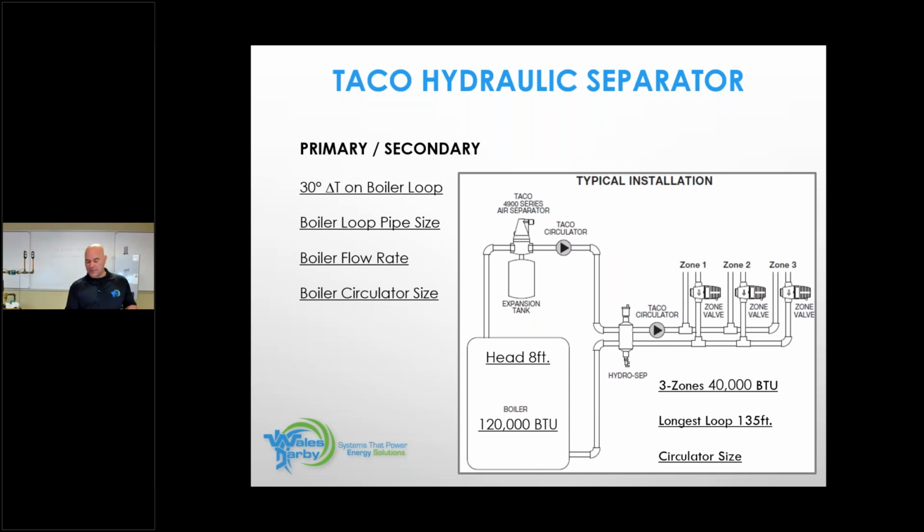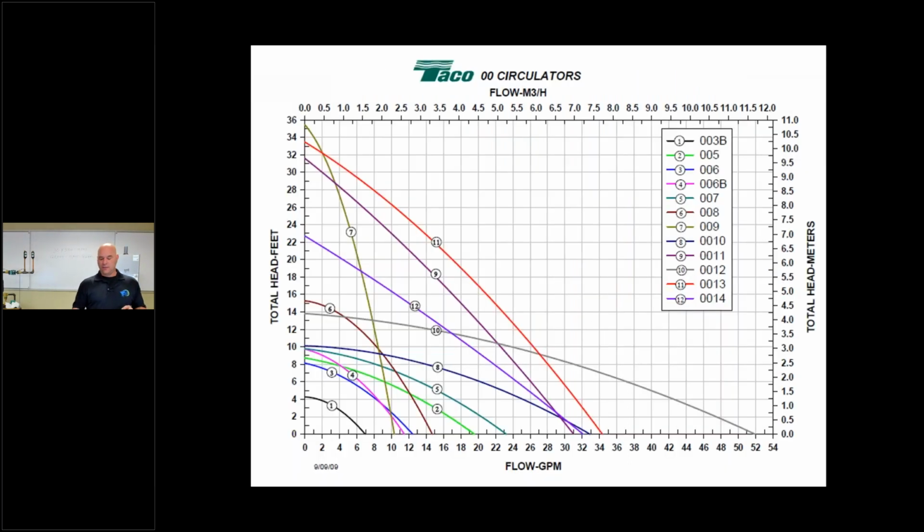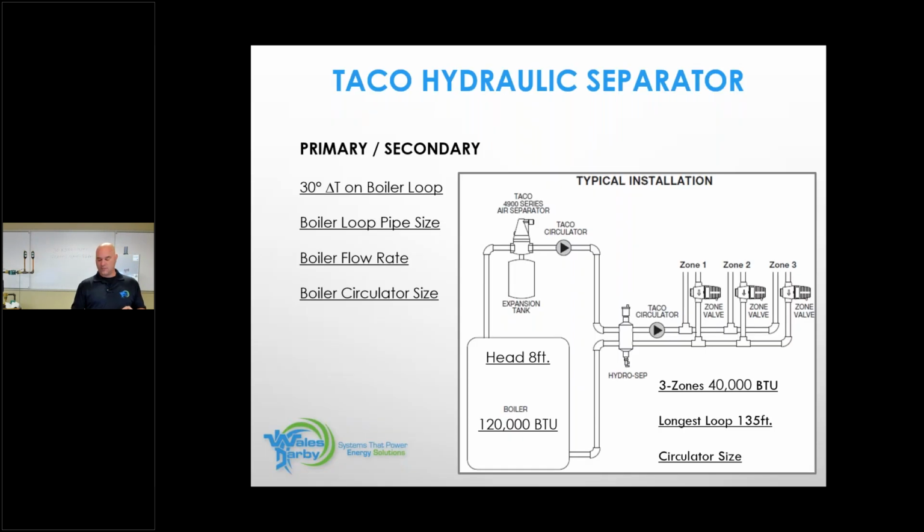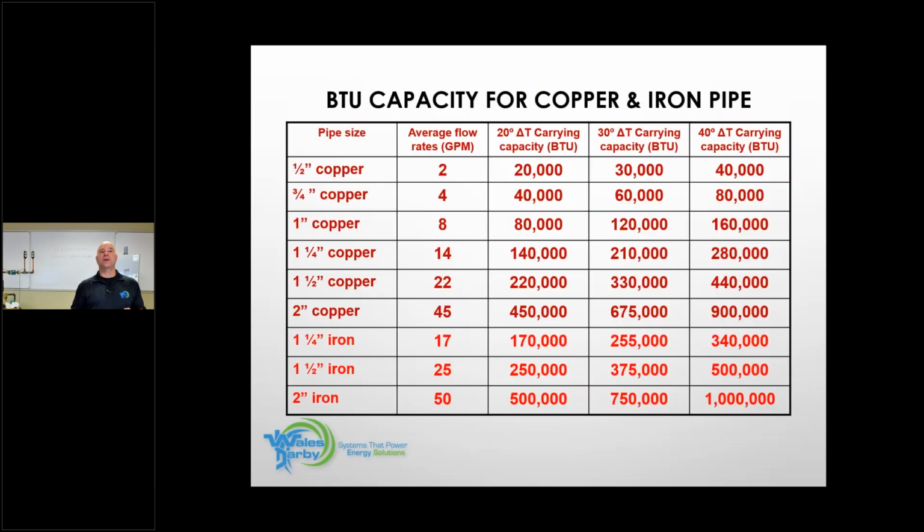So we know the 8 GPM. Okay, so for that gentleman, I'm going to go to this chart. He picked an ECM, by the way. Okay, good. So right there, what is the flow rate for 8 GPM? Is everyone happy with 1-inch pipe?